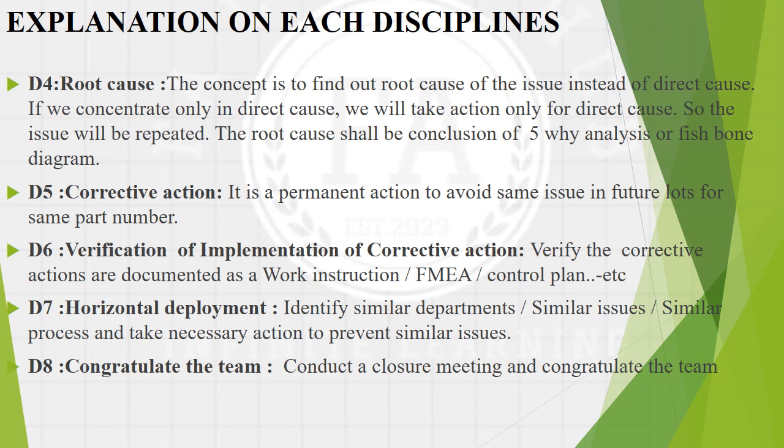One of the possible answers shall be the issue may have been identified during testing, but the operator missed putting a permanent marking or permanent scratching on this particular defective harness. This may be the issue. So why did the operator not put permanent marking, permanent scratching or permanent damage on the defective harness? The reason may be that he did temporary marking, and during cleaning it may have been erased. This may be the reason.